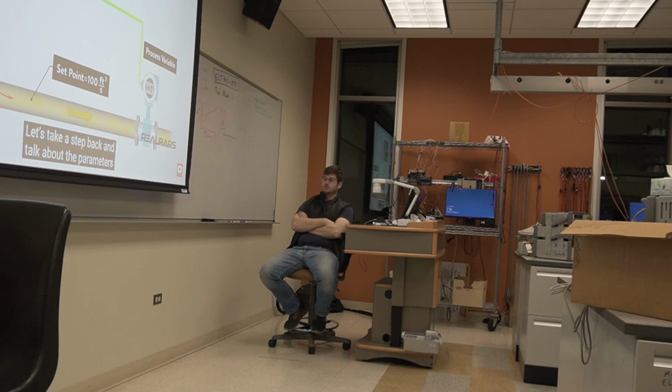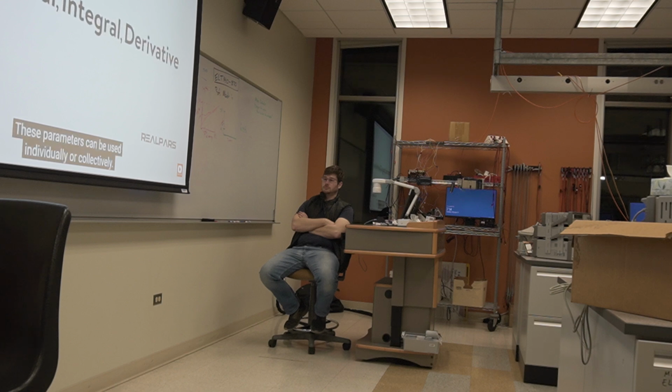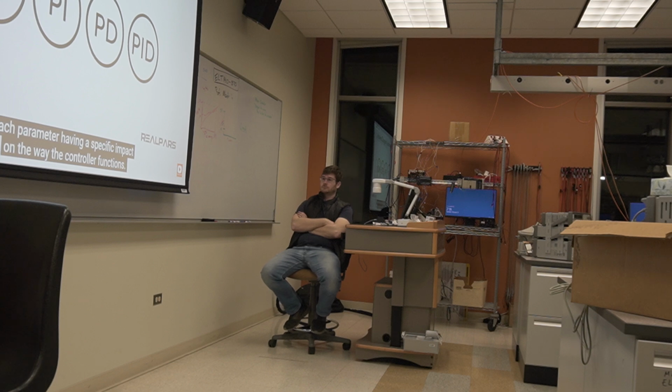Let's take a step back and talk about the parameters that we will be adjusting for our control. First, the PID term, as stated earlier, stands for proportional, integral, and derivative. These parameters can be used individually or collectively, meaning you can have just a proportional controller, a proportional and integral, a proportional and derivative, or of course, a proportional, integral, and derivative controller. Each of these parameters is enabled and adjusted individually, and each controller type would be used for specific purposes, each parameter having a specific impact on the way the controller functions.